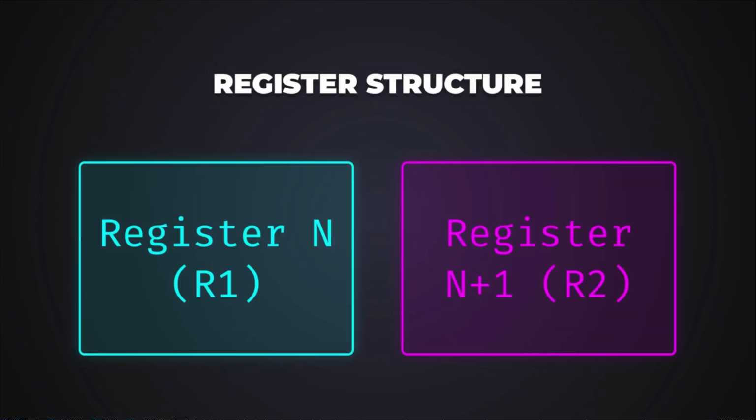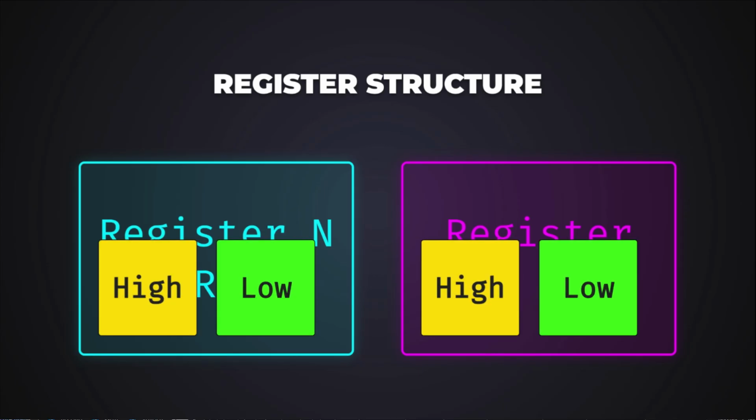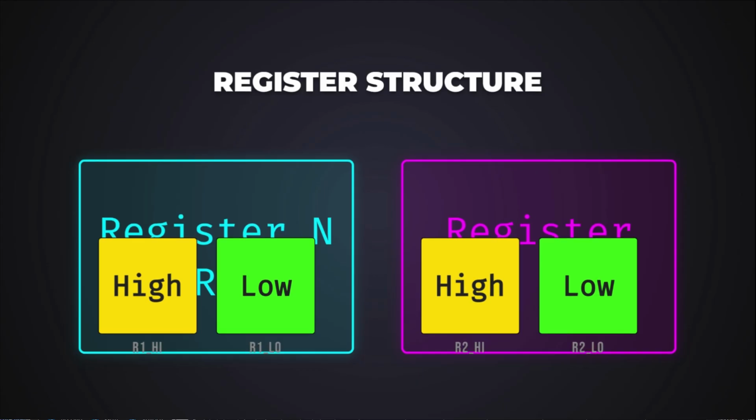When requesting a 32-bit float starting at address N, the Modbus master receives data from register N and register N+1. Let R1 be the 16-bit value from register N, and R2 be the 16-bit value from register N+1. Each register R consists of 2 bytes, B high and B low. Standard Modbus uses Big Endian byte order within the 16-bit word, meaning B high is the most significant byte. The 4 raw bytes are R1 B high, R1 B low, R2 B high, R2 B low.